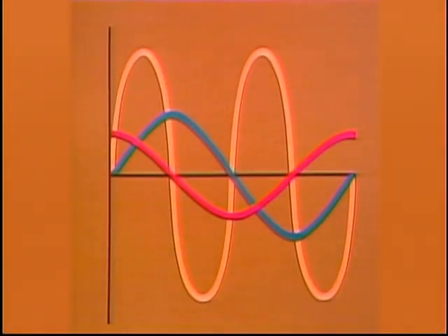The same thing is evident in a purely capacitive circuit. As we saw in segment 3, in a capacitive circuit, current leads voltage. We can go through an AC cycle for a capacitive circuit the same way we did for an inductive circuit and see what happens to power when this out-of-phase condition exists. During the first quarter of a cycle, both current and voltage are positive, so power is positive.